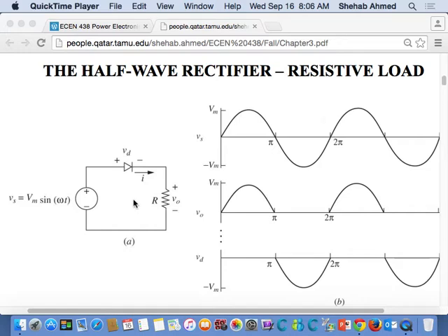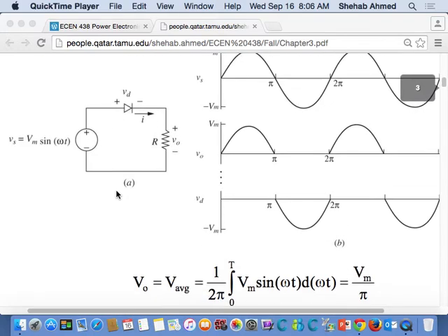We went through that, and again, the objective of these rectifiers is to create DC from the AC input, right? So definitely there's an interest to calculate the average value, which is the DC value that we want to calculate as the output. We would like to know what DC value I can put across my load. So the DC value is the average value, which is 1 over the period. In this case, the period is the full cycle. I have voltage on the output during half of that, and then it's 0 the rest of the cycle.